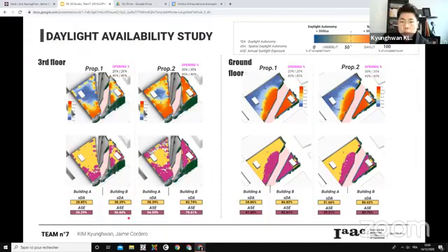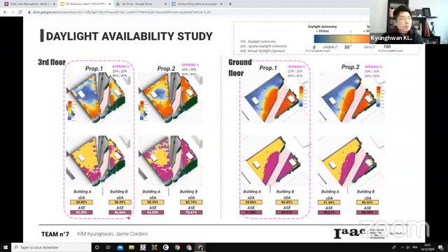Yeah. So after making our proposition for clients, we thought about how we could decide a better design. For us, the daylight availability study was the decision maker by predicting the interior thermal comfort for users. The red color represented the zone of over 50% occupied hours by daylight autonomy at the test of annual sunlight exposure. The first proposition area is better because the purple color represents that there is less potential area for glare or overheating by daylight.